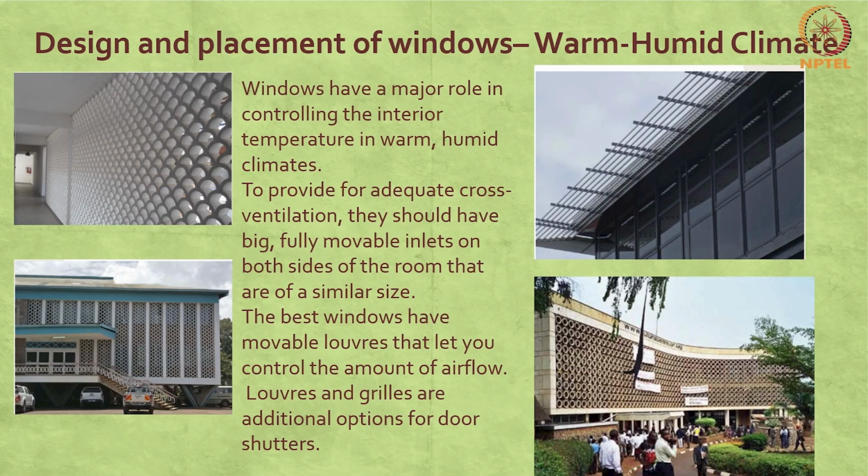Positioning windows in accordance with the direction of the predominant winds will allow natural ventilation throughout the interior space. Concentrating this airflow at body level maximizes its effectiveness. The ideal position for bedroom windows is to pivot or raise them to the level of the bed in order to direct airflow towards the sleeping surface.